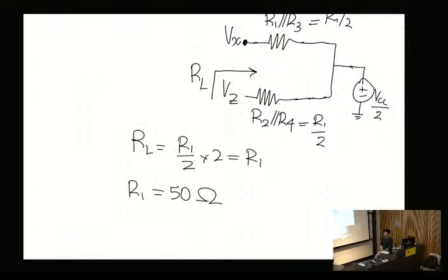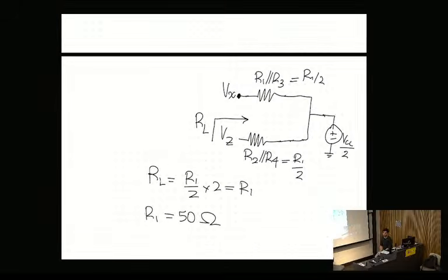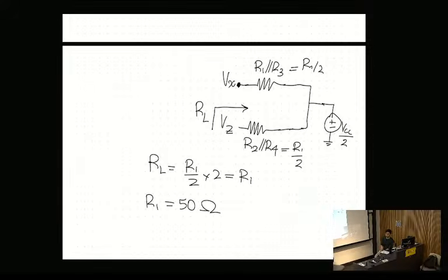So a very long way of getting to it, but this is quite a tricky question. The trick is that you have to develop an equivalent circuit model. When you're considering any sort of load resistance, you need some sort of circuit model, so that should be your first goal in calculating these impedances. Usually we use the Thevenin impedances in the case where you're trying to model one circuit and squeeze it down into one resistance and then fit it into a circuit like this. But in that case, we don't really need to apply that method.